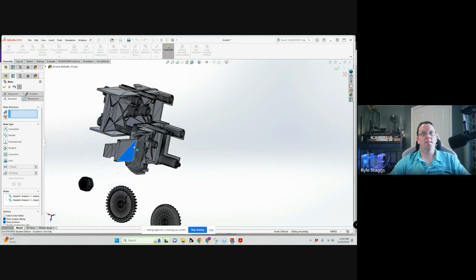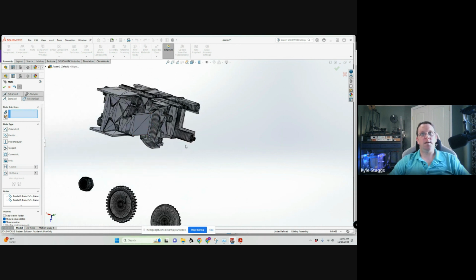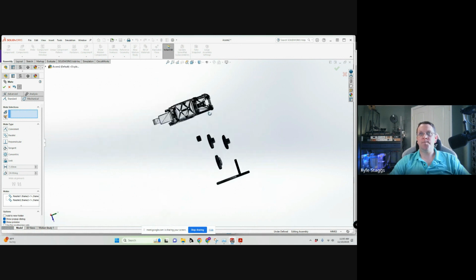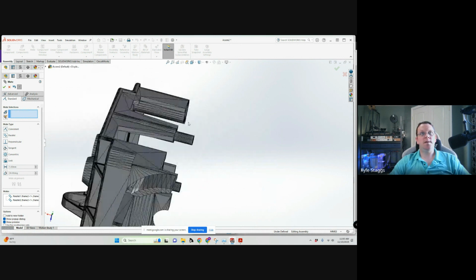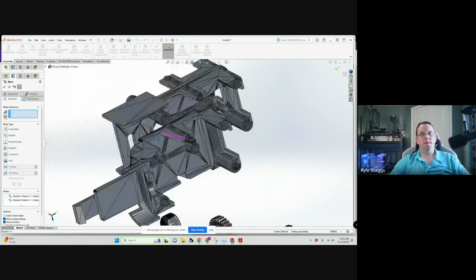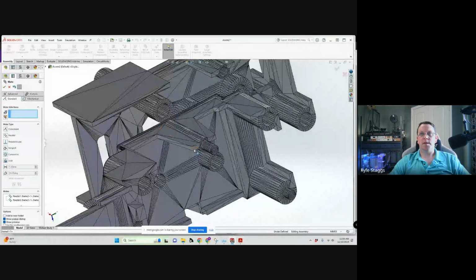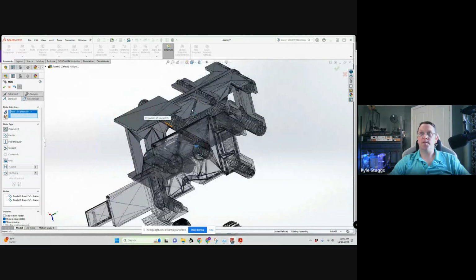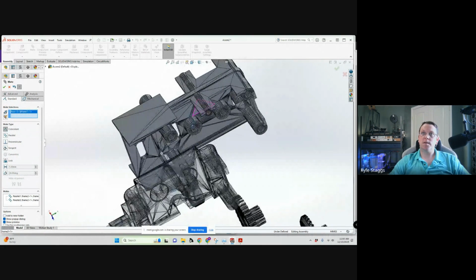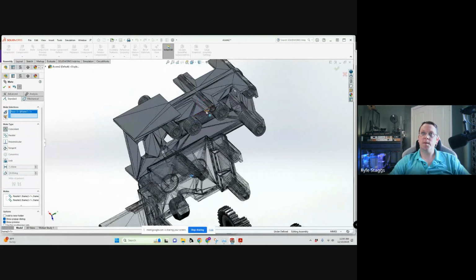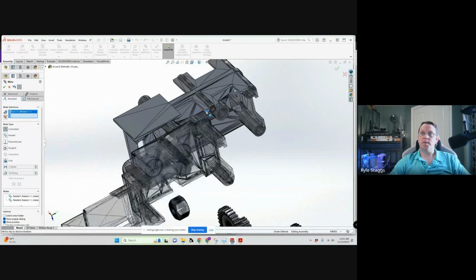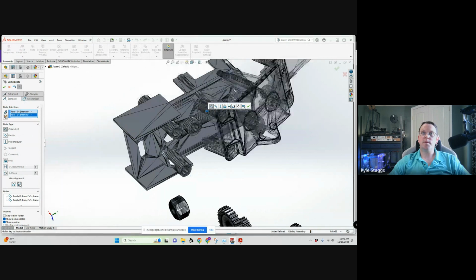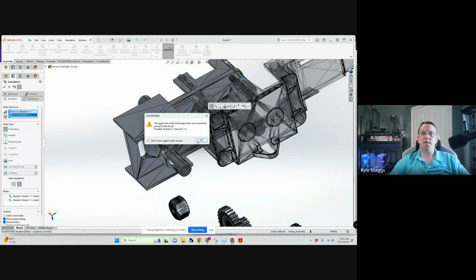This now I can flip in orientation by saying this face is going to be coincident with this face. Flip orientation.